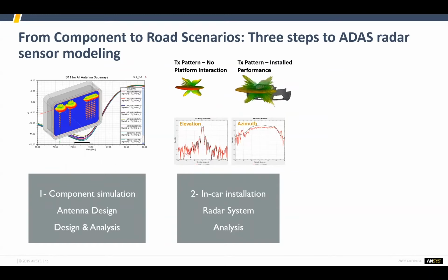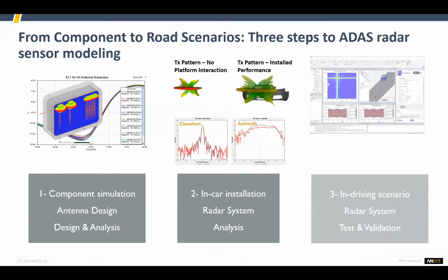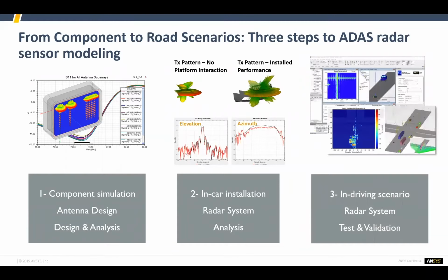And then the last thing that we have to do is post-process the information, right? So we install our antenna on a vehicle, we then move that vehicle through a street scene, and as it's moving through a street scene, we do some digital processing, and of course we do electromagnetic simulations so that at every step of our movement, we have an accurate electromagnetic description of our environment, and we use that information during digital post-processing to come up with a range-Doppler plot.